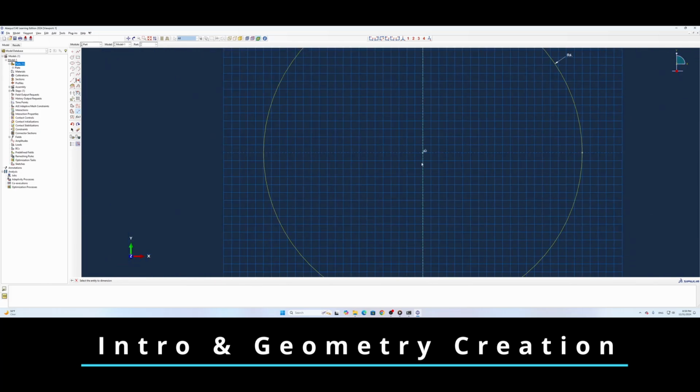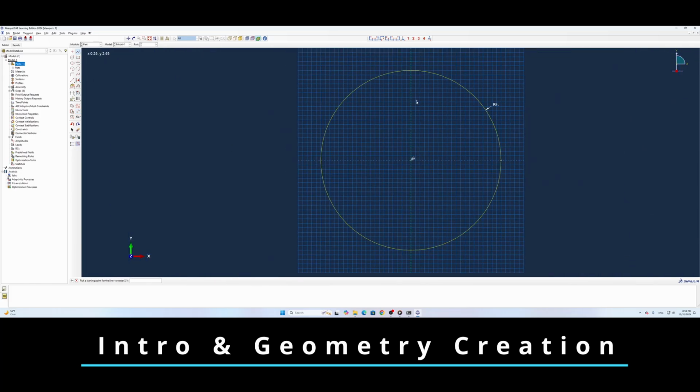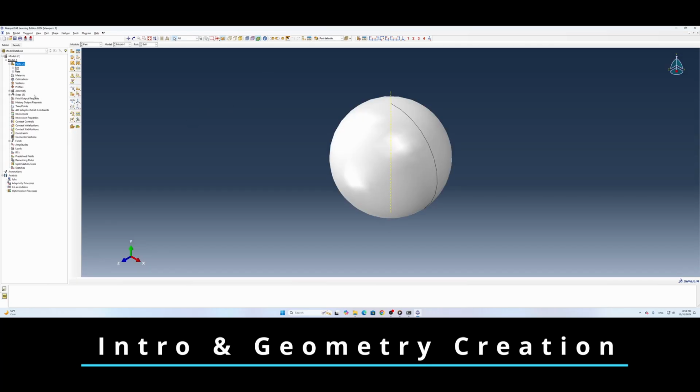So 4. After that, I'm going to draw a line to cut the circle in half from here to here. Then I can remove the lines I don't need. I don't need this line. I don't need this line. As you can see, right now we only have the half circle left. I'm going to have this half circle revolve along this construction line for 360 degrees. So hit OK, OK. 360 degrees to make a sphere. All right, so now we have the ball.